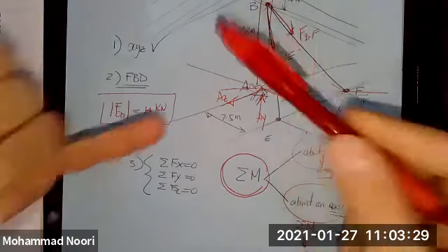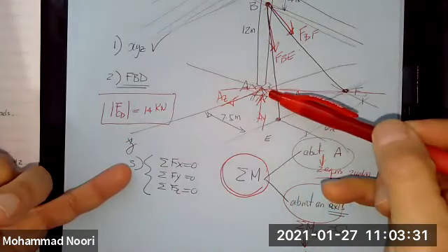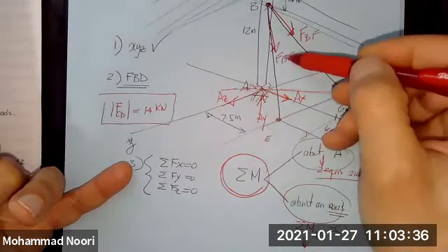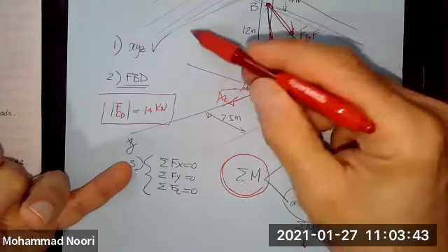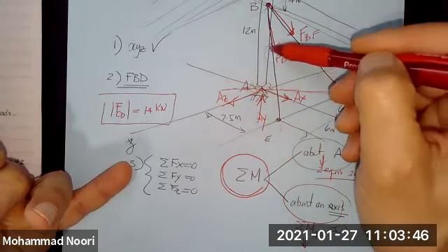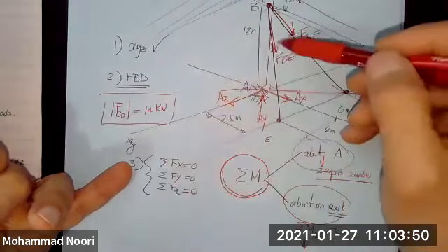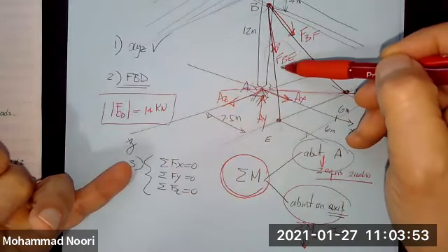I have a quick question. For the moment about the axis in red, you said there was one unknown. Which unknown is that again? This one and this one and this force all intersect. But how about the FBE? It's not intersecting, so that's the only unknown. This one is given, so that's not an unknown. So you only have one unknown and one equation.